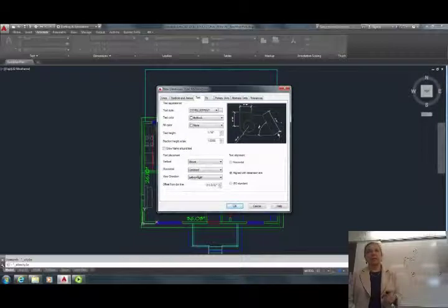We're getting somewhere. What looks funny right now? My text is smaller, but my ticks and all of the other settings are a little bit big, right? So I'm going to work on them. Is there anything else here? Offset from dimension line. There's a few other settings here, which is extensions here, and offset from dimension line. I'm going to reduce this gap here. Okay, I know it's very small, but offset from dimension line.